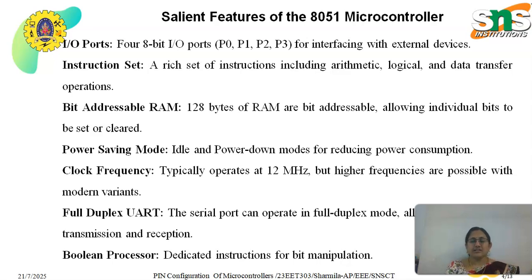And the 8051 architecture has a rich set of instructions. It includes arithmetic, logical and data transfer operations. The next one is the bit addressable RAM. In this, 128 bytes of RAM are bit addressable, that means it allows individual bits to be set or cleared.